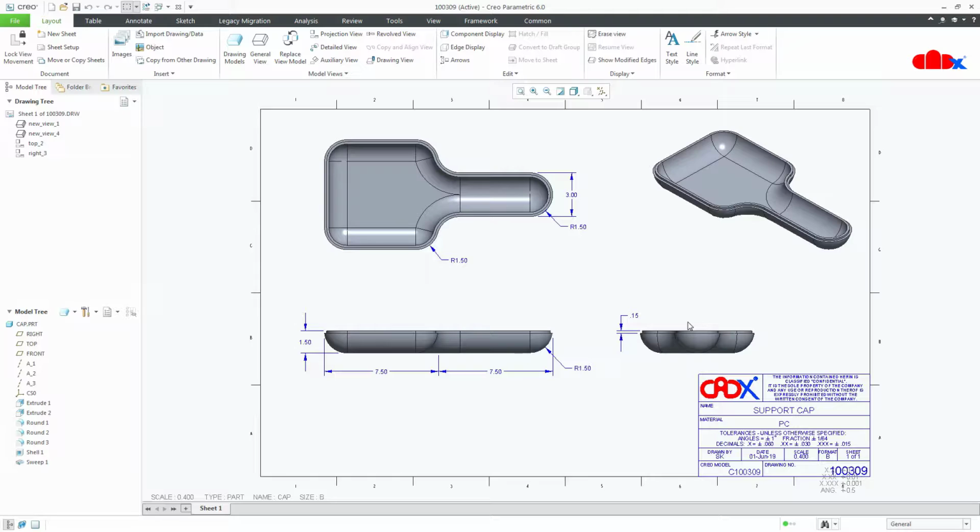So let's talk about the drawing format first. When we talk about the drawing format, it includes everything available in the drawing except the drawing views and the things related to the drawing views. That means it includes your title block, it includes your entire border, it includes your standard note if you have, and it may include some other stuff also.